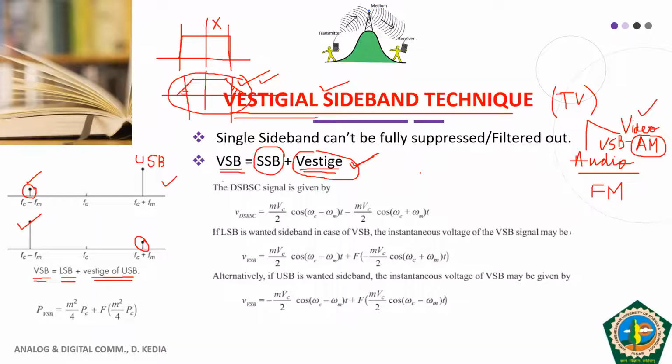So some portion of the lower sideband or upper sideband, whatever vestige we have chosen, we keep along with the other sideband. Since we keep a portion of the other sideband, what will be the power requirement? The power requirement is the power requirement of single sideband, plus the power requirement of the fraction of the second sideband. F means fraction, some portion, not the complete one. So this is your vestigial sideband technique.